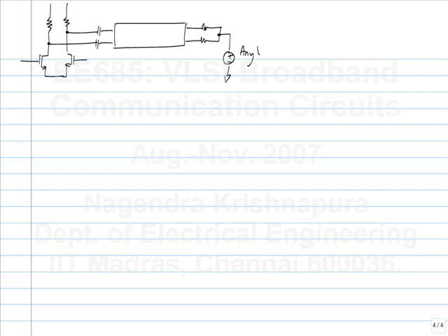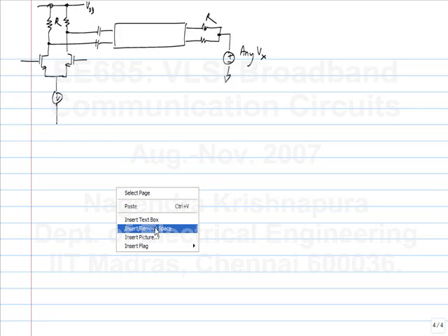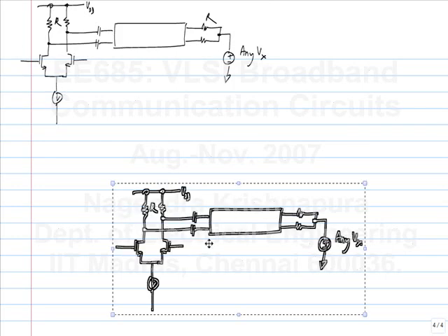You do AC coupling, and once you do AC coupling, on this side you can connect it to anything you want. Okay. It won't affect the transmitter. This is VDD. Okay. And let's assume equal termination.